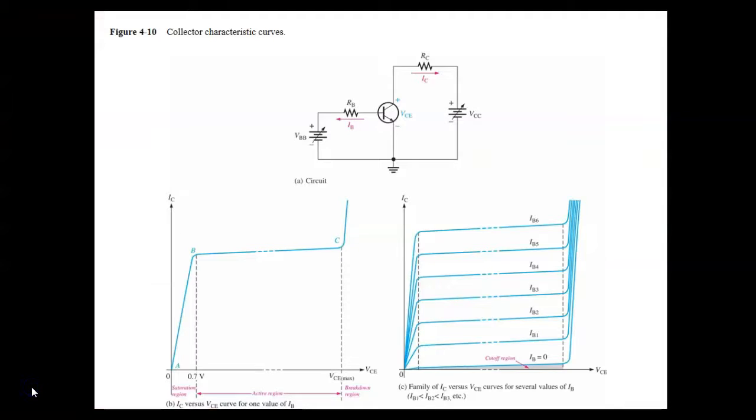This at home, because we've made everything that you need to do, these are referred to as collector characteristics curves. And if you look at your chart, down at the bottom, you got VC is equal to 1 volt, which we didn't do. We did 2, 4, 6, and 8. Everybody see that across the bottom? Up the left-hand side, this is where you're going to put your ICs.